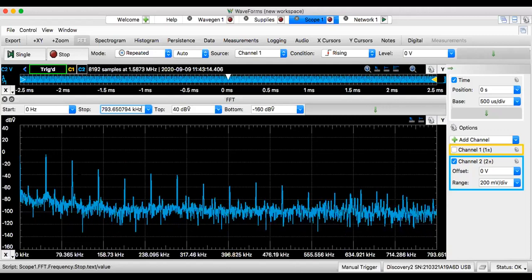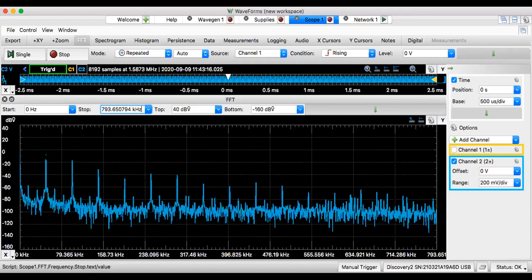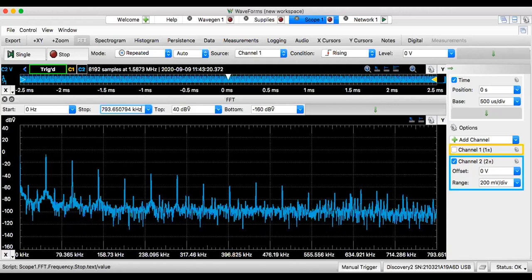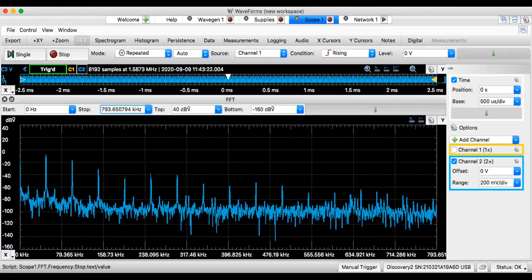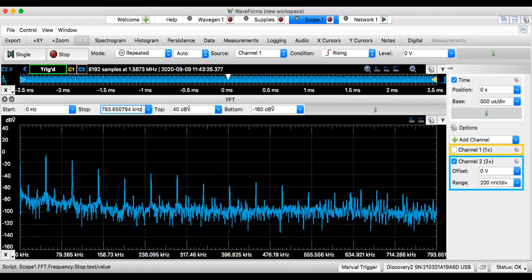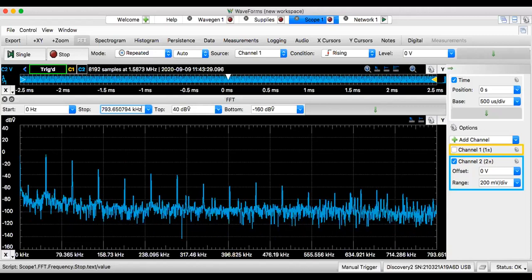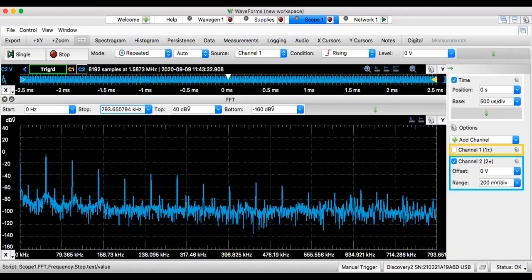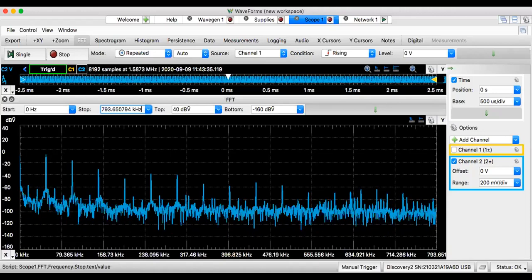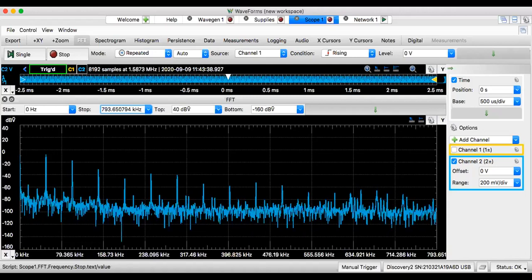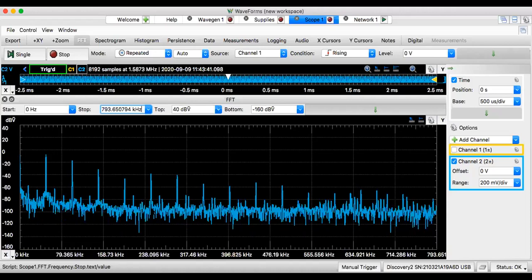Notice the frequencies are multiples. If the input is 50, multiply by 2, by 3, by 4 that's 200, by 5. Those are called harmonics. So distortion appears as harmonics, and that's why it got the name. The reason for distortion is that the output has too many harmonics.